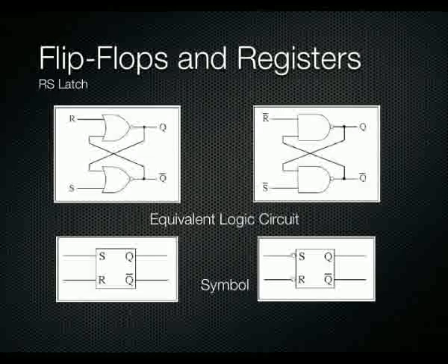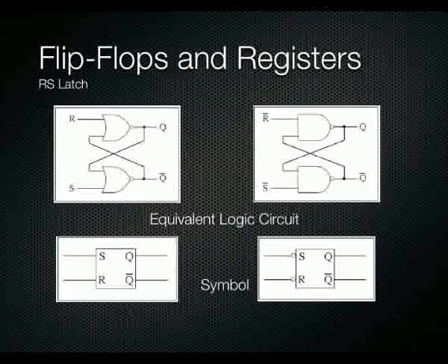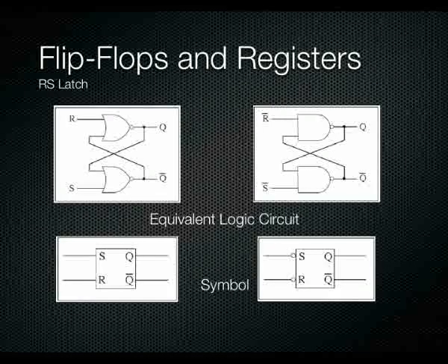You can see if you make it from NOR gates, the R and S inputs are simply R and S. If you make it from NAND gates, then the R and S inputs are actually negated. So you've just got to keep that in mind. Depending on which way you implement it, out of NOR gates or NAND gates, the S and R inputs will change.